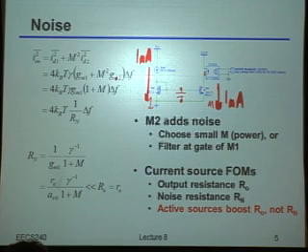Okay? Now, as I mentioned a second ago, this is actually a very good idea anyways, because as we were discussing, what you really want is, at the end of the day, when you created this voltage here, you want the impedance of that voltage source to be as low as possible, right? Because it's supposed to be now a voltage source. So putting a big, huge cap on it to make sure at least the high frequency impedance is low is actually a really good idea, right? It'll make sure that even if there's some transient movement on ground relative to, let's say, the rest of the world, that'll keep that gate voltage very well coupled to its own reference potential. Okay? Does this make sense to everybody?